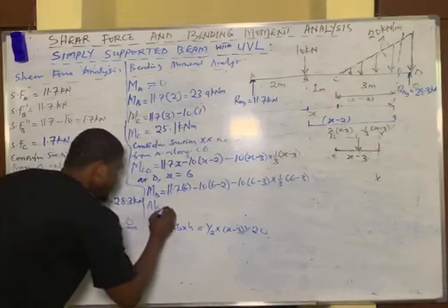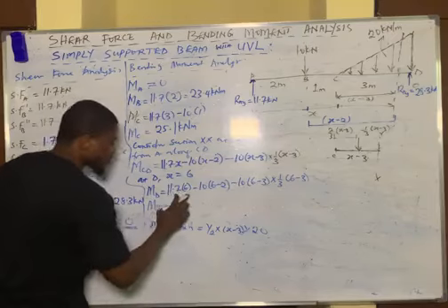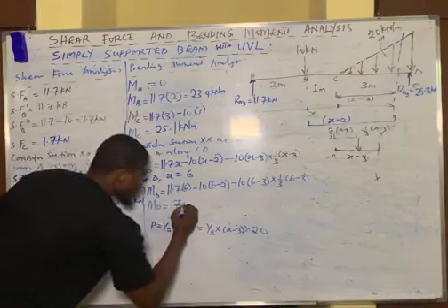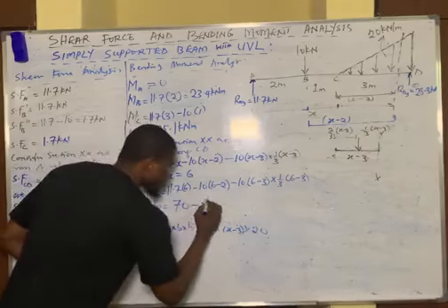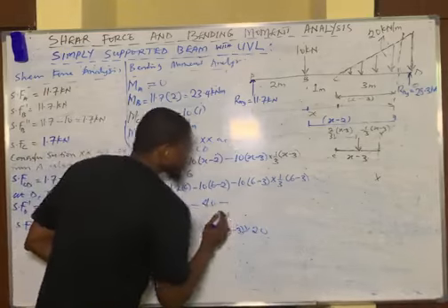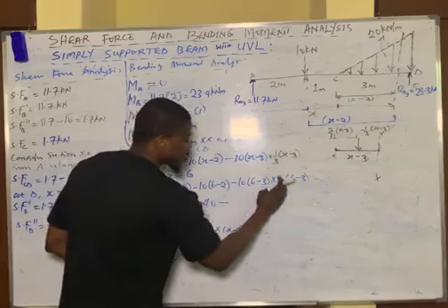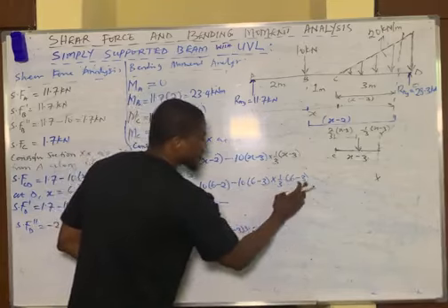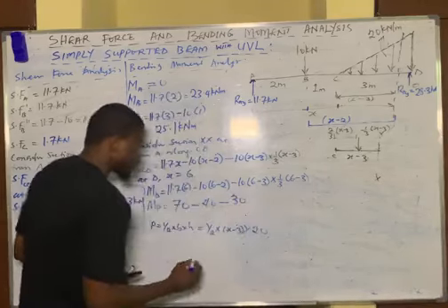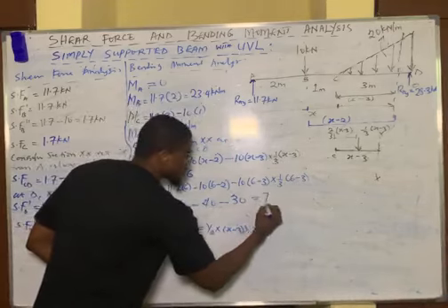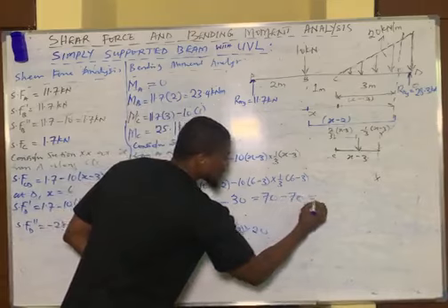Moment at D equals, let's find 11.7 times 6. So 11.7 times 6 is approximately 70, minus, 6 minus 2 here is 4, 4 times 10 is 40. Minus, I have 6 minus 3, that is 3, 3 times 10 is 30. 30 times 1 over 3 is 10. 10 times 6 minus 3 gives us 30. 6 minus 3, of course, is 3. 3 times 10 gives us 30. So you can see already from here, this is equal to 70 minus 40 minus 30, which is minus 70, and this is equal to 0.